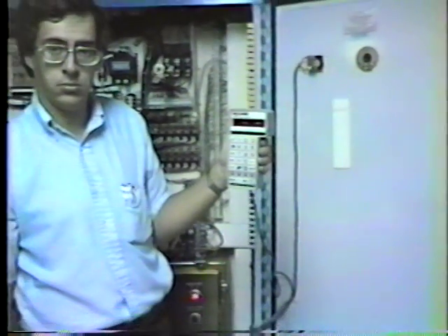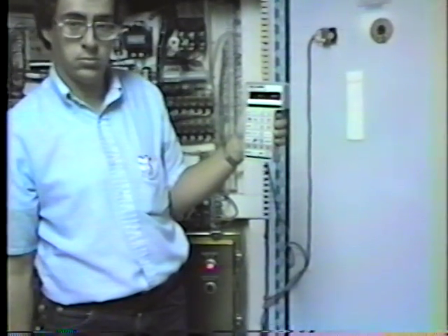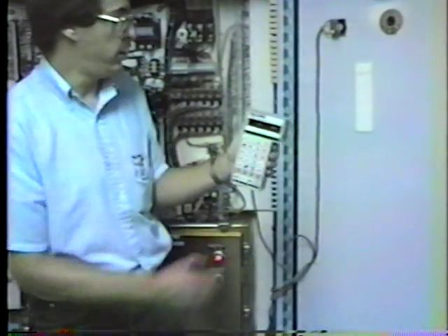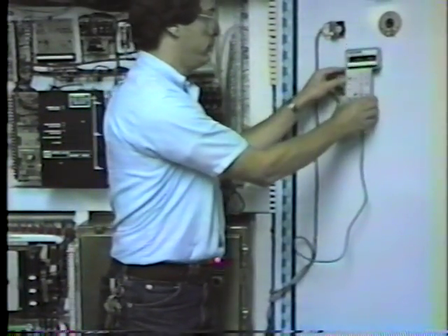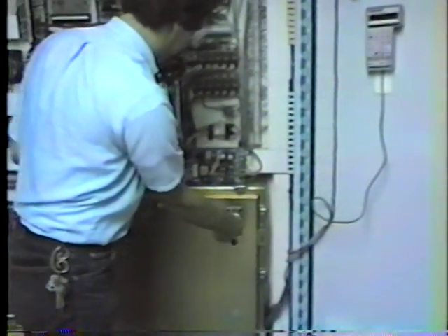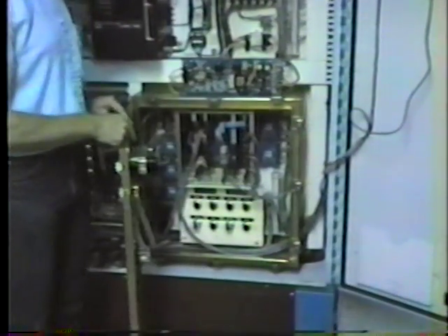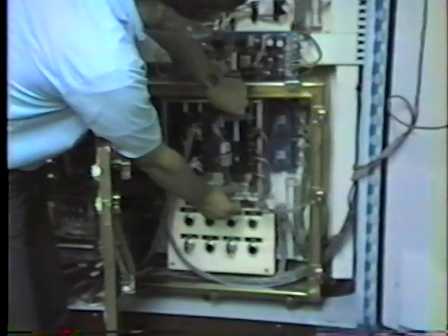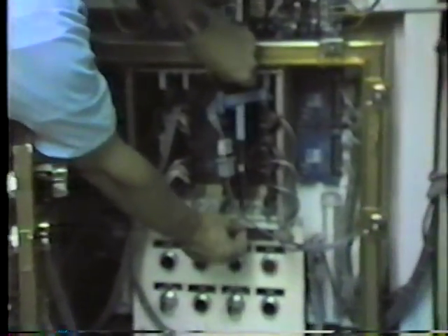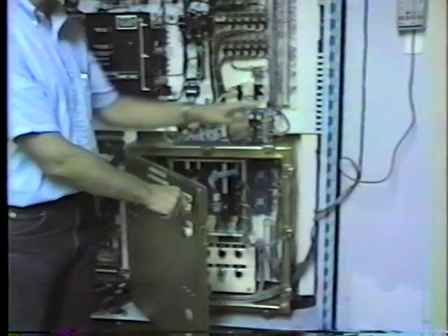For right now, would you please cause the computer to fail by removing one of the boards? All right, what I'm going to do is turn off the power of the computer, and I'm going to pull the analog to digital converter board. I don't even have to get it out of the cage, just loose from the back point. Okay, it's now loose. Notice that we've had a failure of the built-in test. The light above the BIT button should come on, and the mill will not operate.